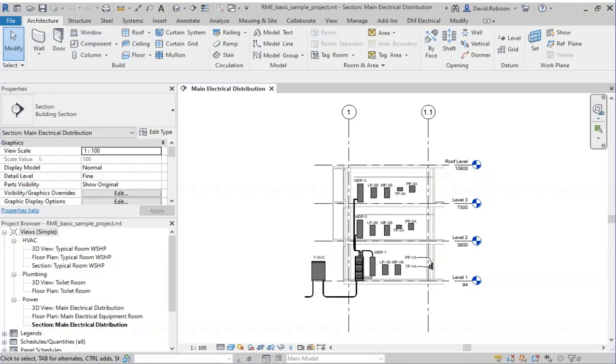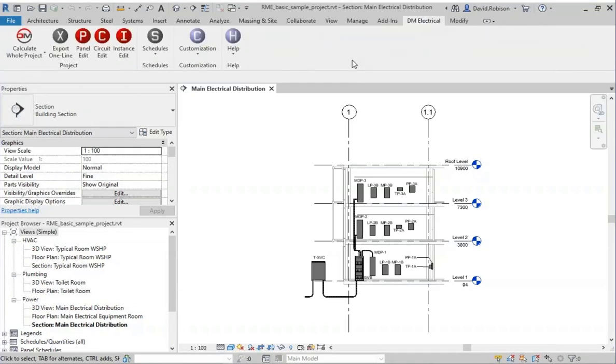So I've got two support questions that have come in that I thought would be interesting to talk about. The first was someone asking for their conduit sizes. They want their conduit sizes on their wire callouts to be one size larger than the minimum, and they want to know if the software could calculate that for them automatically. The direct answer is no, we don't have a way to choose upsize all conduits by one. But there is a way you can make it happen with a little bit of work in your customization.